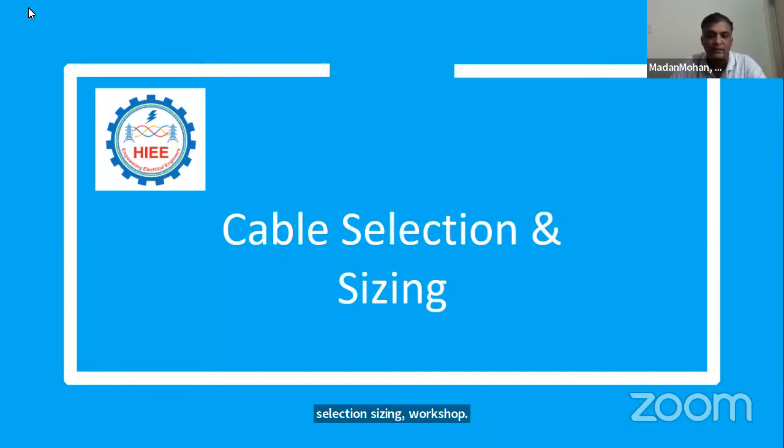Yesterday we discussed a few basics on cable selection, like what the different types of cables are, types of insulations, armoring, and cable nomenclature. Also, we have initiated how to do the cable sizing calculation.